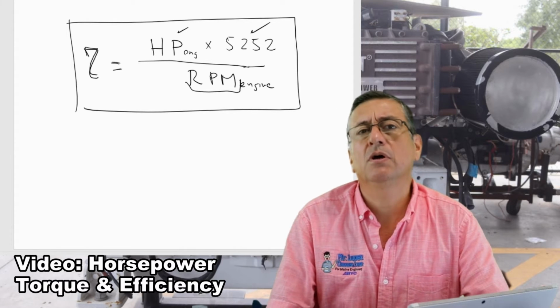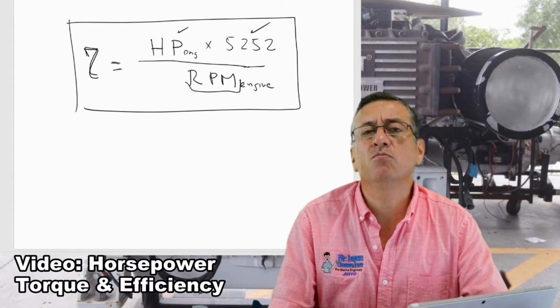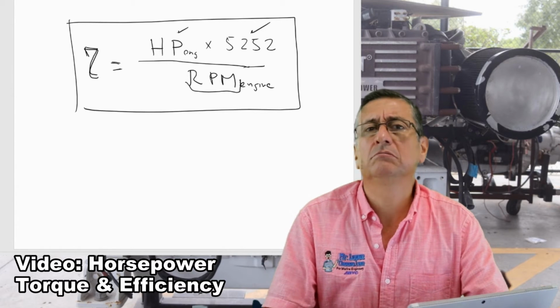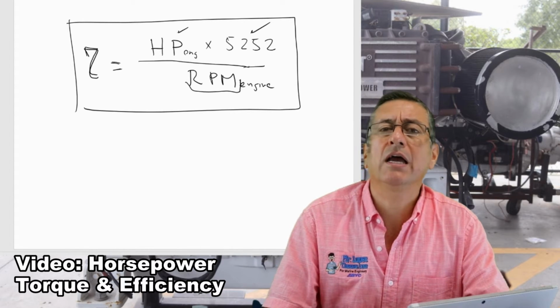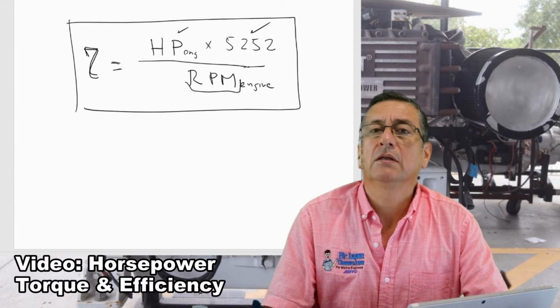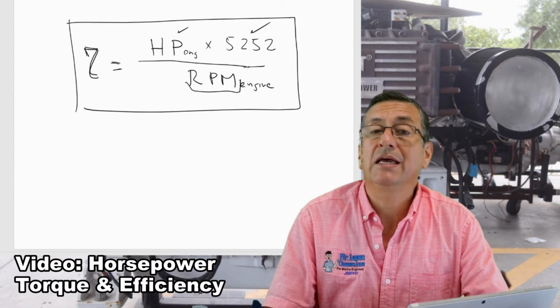This is the maximum RPMs in a typical inboard diesel engine. And what is the idle? The RPMs at idle is normally around 900 RPMs. Right? Keep in mind that this number is very important.